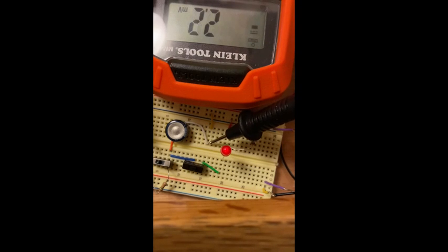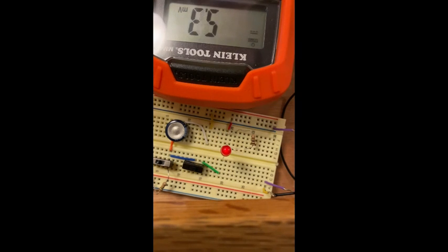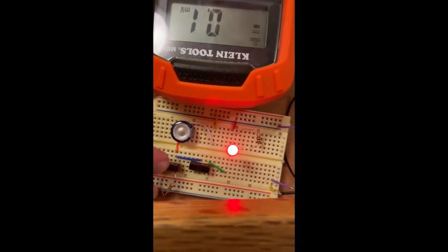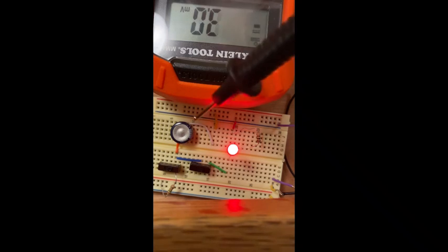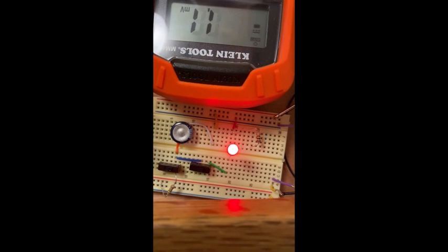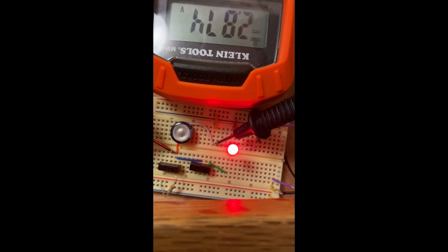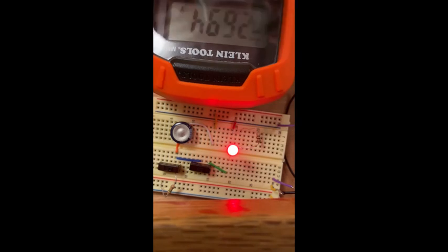You can also see that the voltage across my capacitor is not 0 like it says in the problem. That's because I had a failed take earlier. So switch 2 is already flipped. If we flip switch 1, we see that the light turns on, the capacitor begins to charge. The voltage across the capacitor should be rising. You can see that it's already risen to about the voltage of the battery.